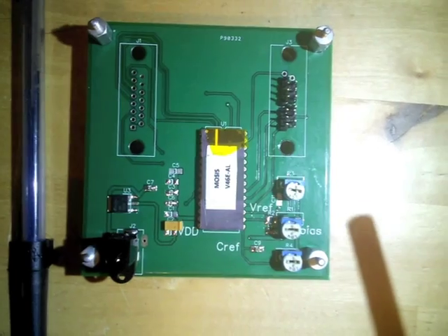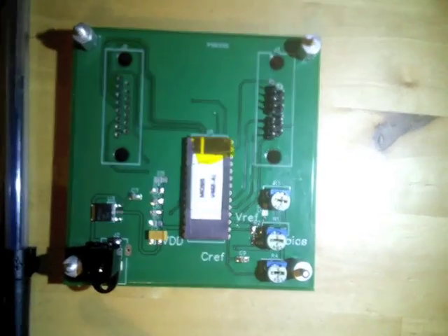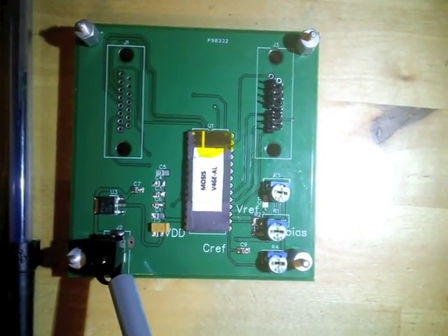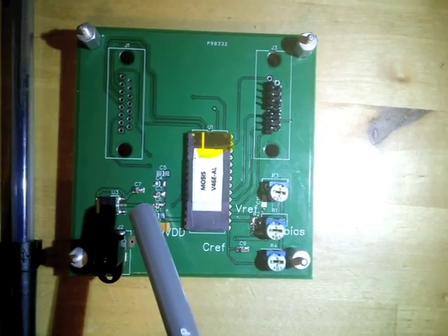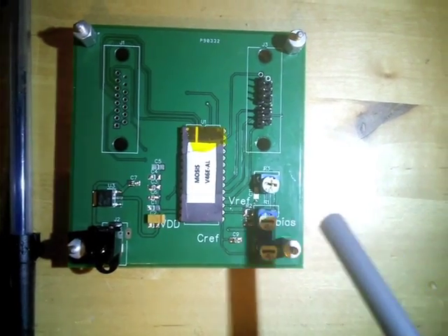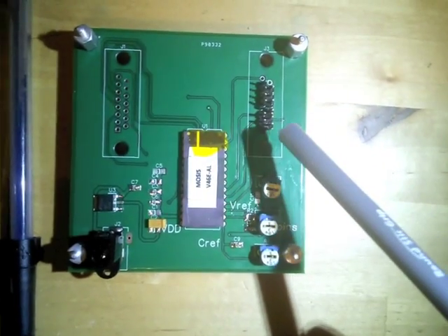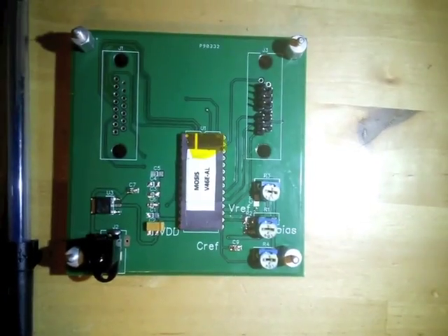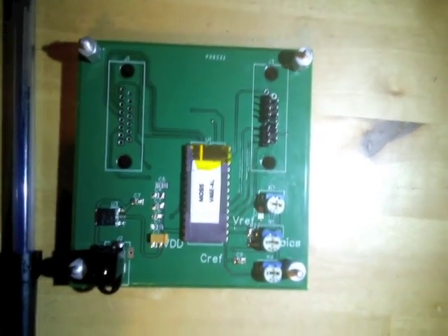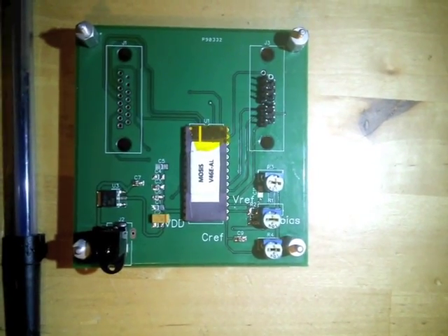Our PCB was developed over 2 iterations and is used for testing and obtaining reproducible results. Our IC is mounted in the middle of the board. In the lower left is the DC input connector. Also on the board is a 1.8 volt regulator IC and decoupling caps. VREF, CREF, and I bias are all adjusted using potentiometers. At the top are two input connectors providing test, output, and control points.